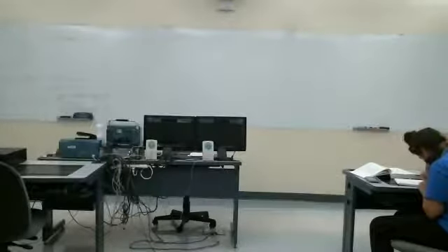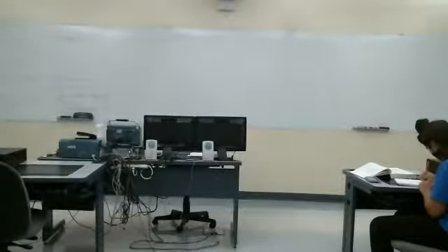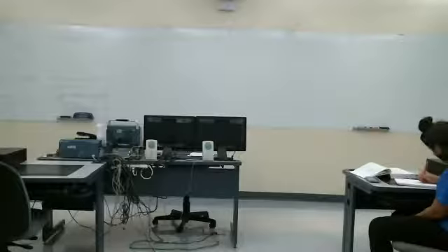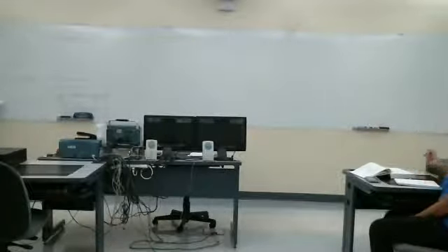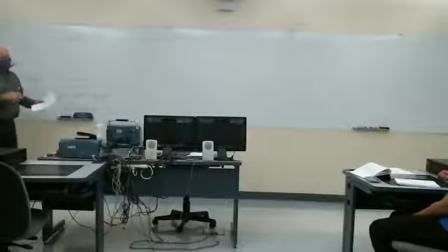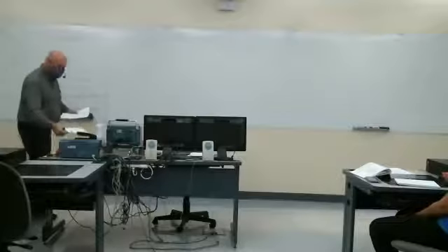If I express the input as a sum of amplitude scaled, time shifted unit steps, then the output is going to be the same time shifted, amplitude scaled step output. So it's a powerful concept that will rely on our circuits having this property throughout this course.